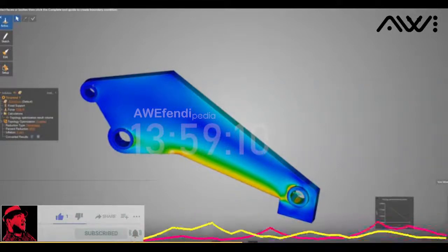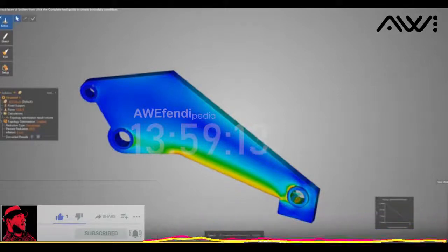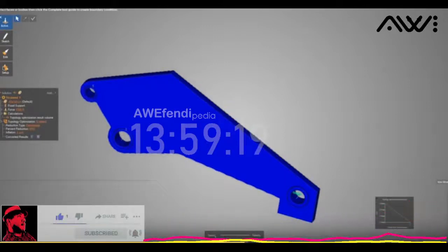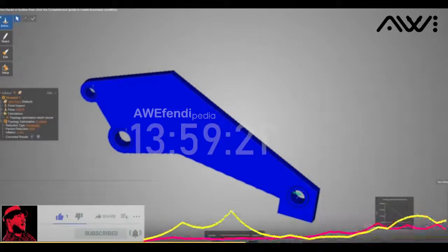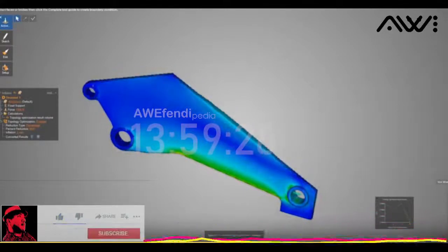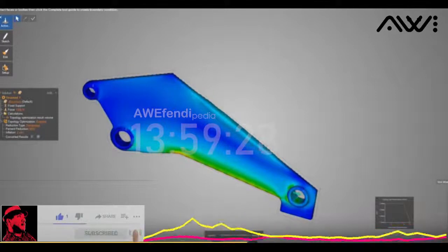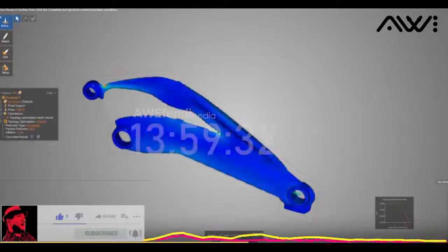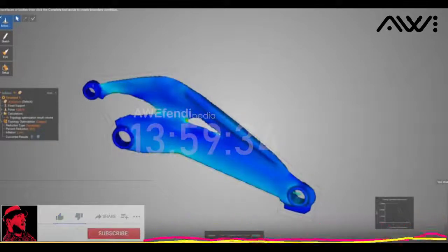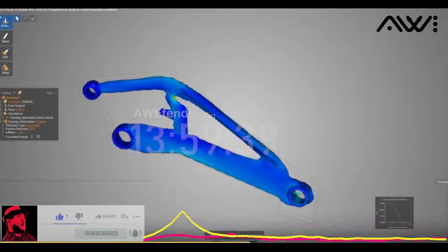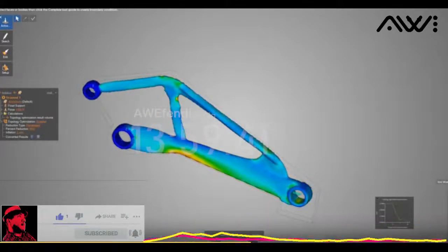Another example too is right above the play. This is where we can change the fidelity, right? Or, I mean, iterating, quick speed, getting an idea, or accuracy, move up the fidelity here. And this is where we're going to start seeing it quick through. Now you can see at the very far right, I have the topology result volume. This is what we're seeing to know, hey, are we getting close to a result? What are we getting here? How does this need to look? This is starting to look like a motorcycle swing arm in some type of fashion, right?